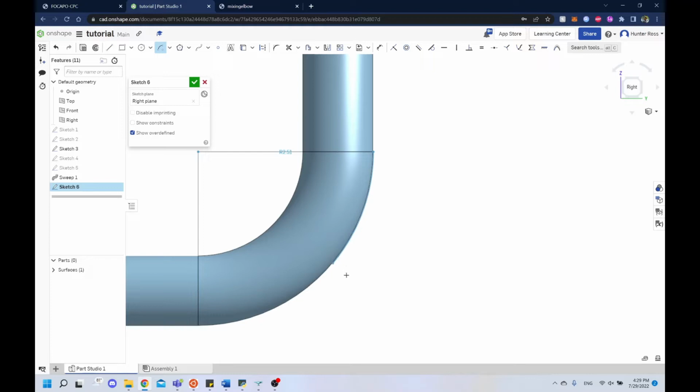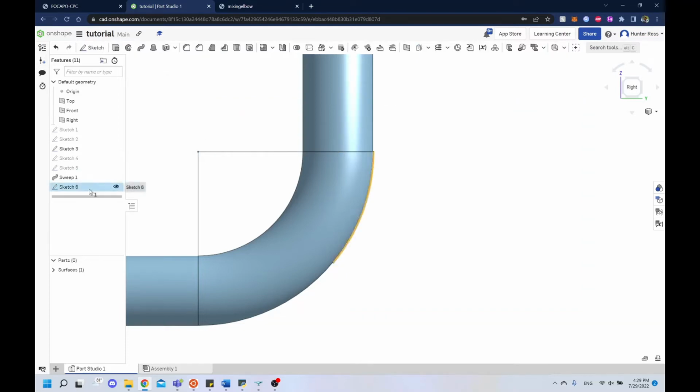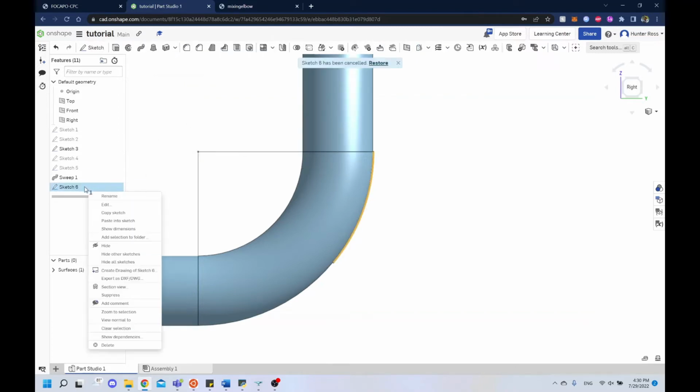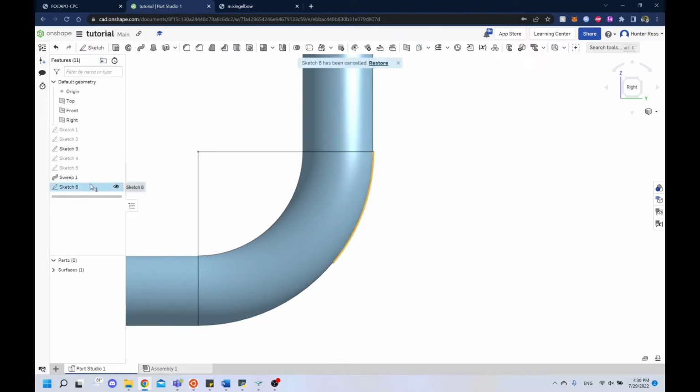And let's see, can we edit this arc? I actually don't know. Let's figure it out. Check mark it. Edit. Can we press D on this arc here? Oh, we can. So we can change this. Let's make it exactly 2.5. Now for the maybe a better way to go about this then would be to delete that sketch, start again, and then let's make a midpoint.